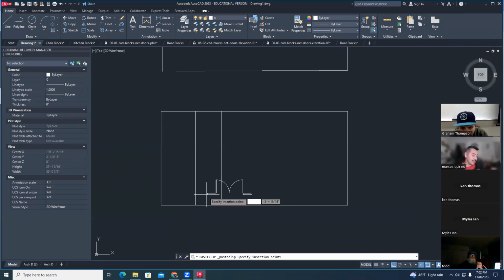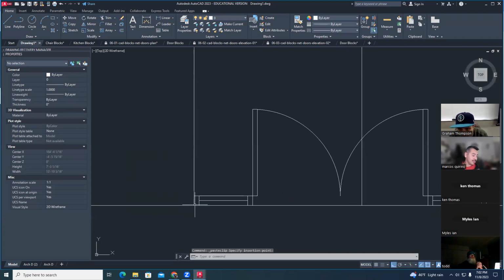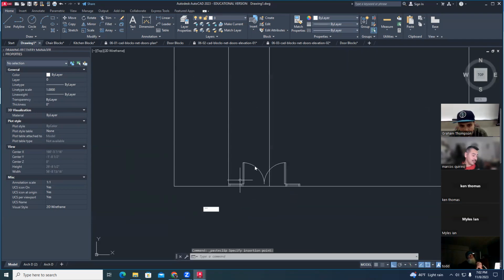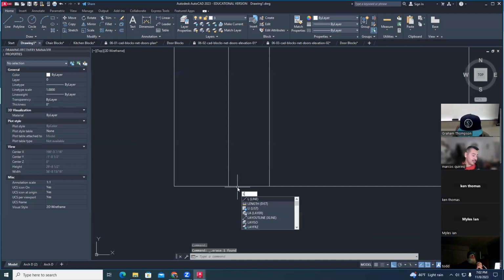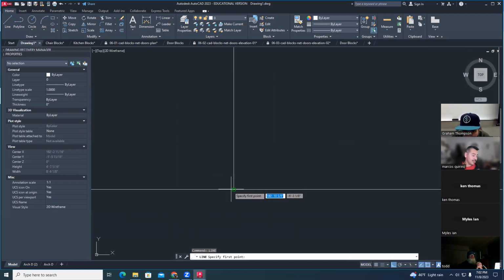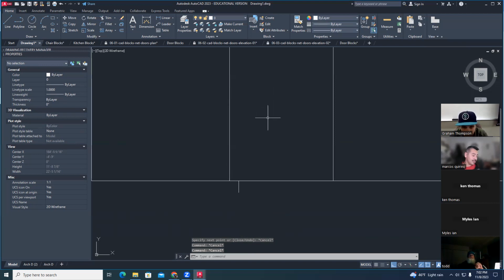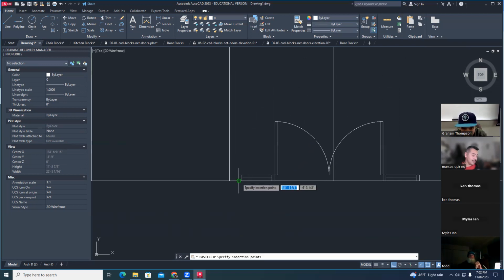Again, pasting it, it wants to drop in right there at the bottom left-hand side. So you could plan your drawing around that if you wanted to bring in a wall, or maybe you knew where the door started. This is where I like to use this. Maybe I know that the door starts 6 inches away, and maybe I don't want to move it later. I can draw a line that's 6 inches away from there. Now I've got a construction line with a point for me. So when I paste that door, I snap it right there and I'm already good to go.